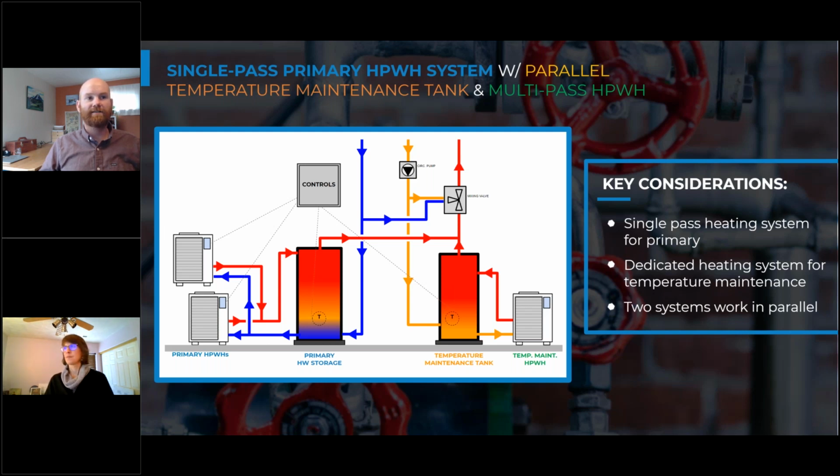Those paraffin wax valves are relying on a medium to expand to close off essentially one side of the piping. And that electronic mixing valve is essentially using a solenoid valve to shut down or open up to control that flow rate. So there's a quicker response with that electronic operation.